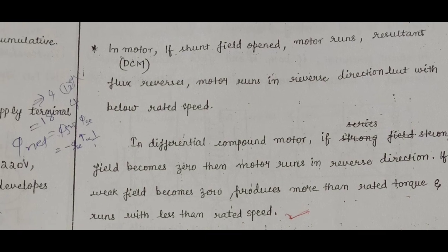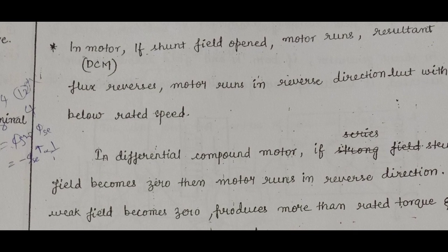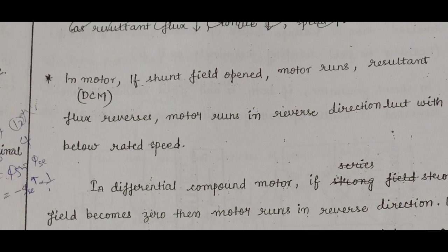In motor, if shunt field open, motor runs as a differential compound motor. Flux reverses, motor runs in a reverse direction but with below rated speed.